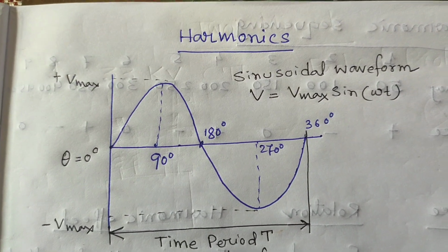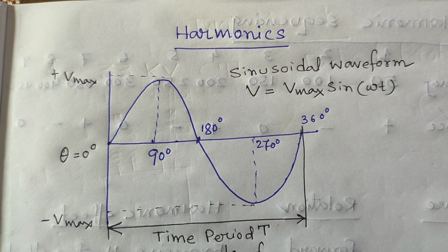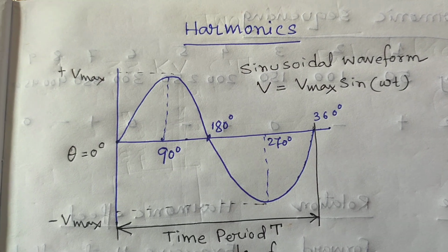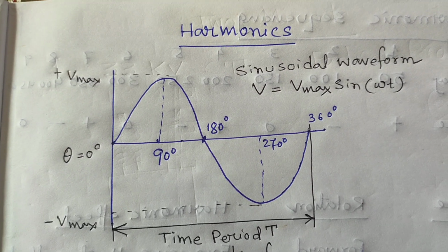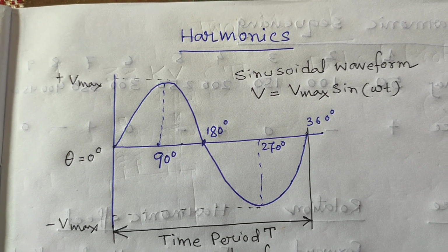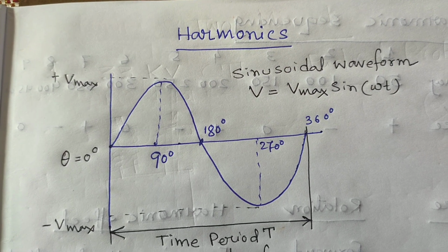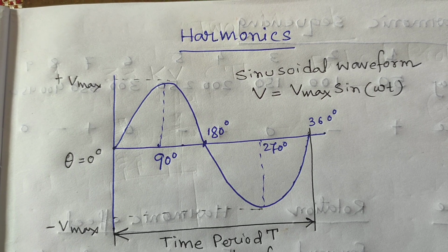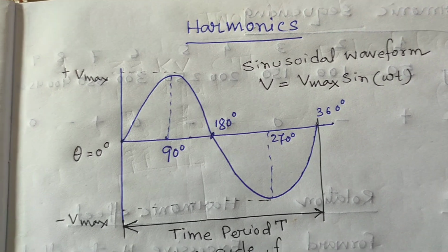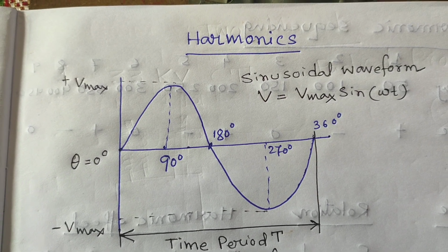These complex waveforms are generated by common electrical devices such as iron core inductors, switching transformers, electronic ballasts in fluorescent lights, and other heavily inductive loads, as well as the output voltage and current waveforms of AC alternators, generators and other such electrical machines. The result is that the current waveform may not be sinusoidal even though the voltage waveform is.